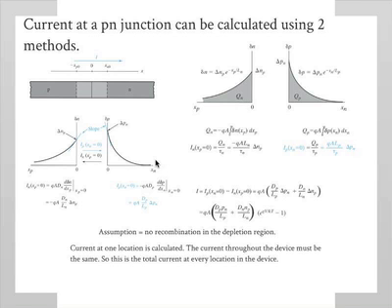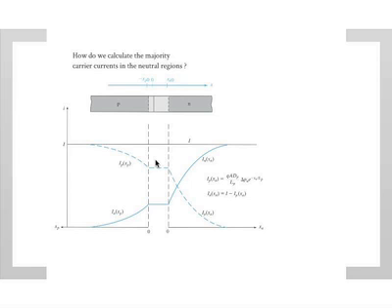But there is current, right? There's current flowing here. How is that flowing? The only likely explanation is the majority carrier, the drift current from majority carriers. Something has to flow here. So the question being asked is, what is the physics behind that flow? What's carrying the current here? Essentially the majority carrier. And we can look at this in this interesting plot.